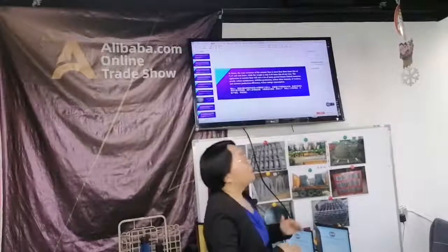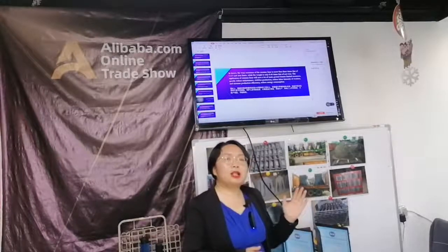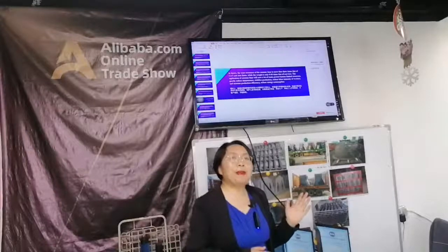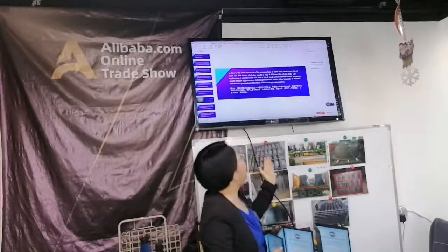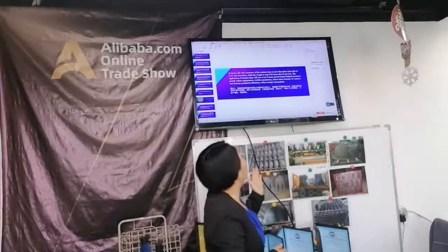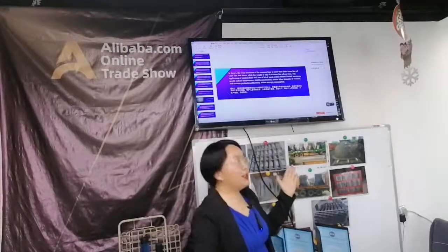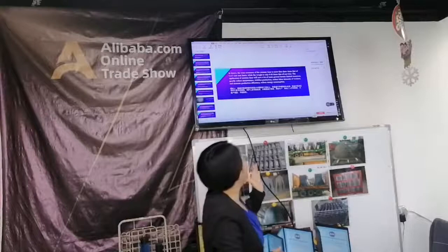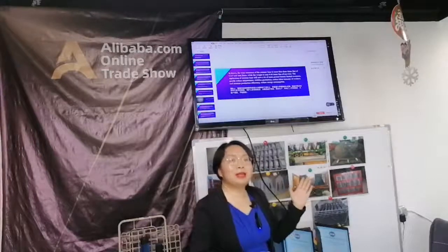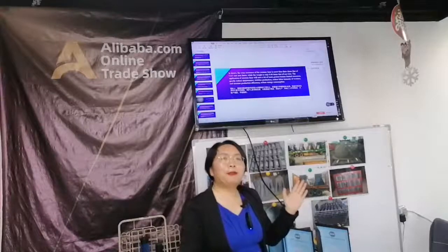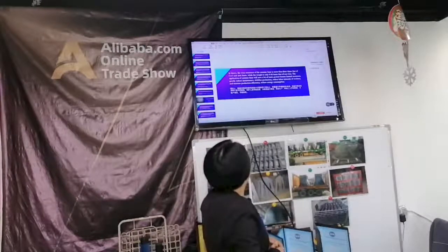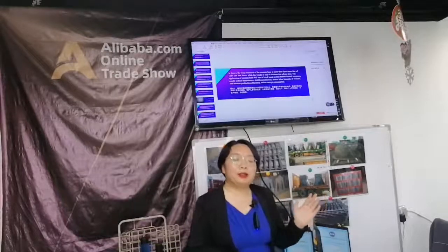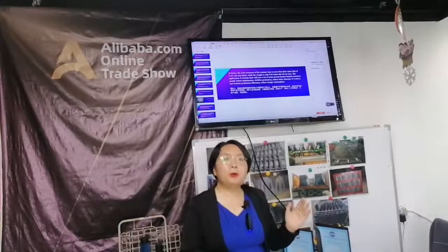Okay, the unit weight of ceramic liners is very light, just 0.46 times that of high chrome white iron liners. Very light. Also, its wear performance is at least four times that of high chrome white iron. Also, you know, ceramic liners are not metal elements.